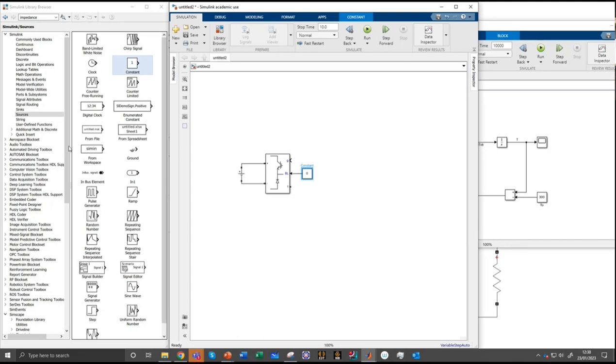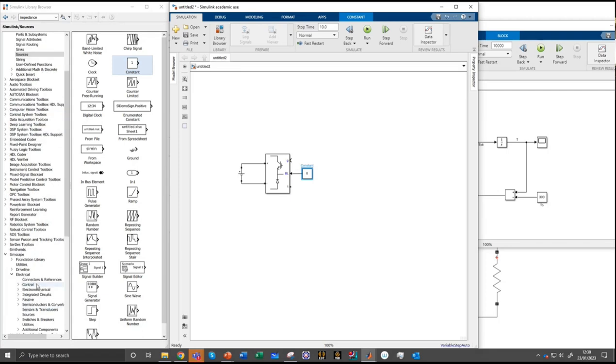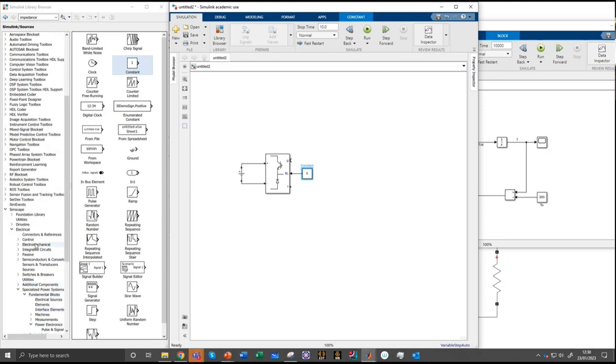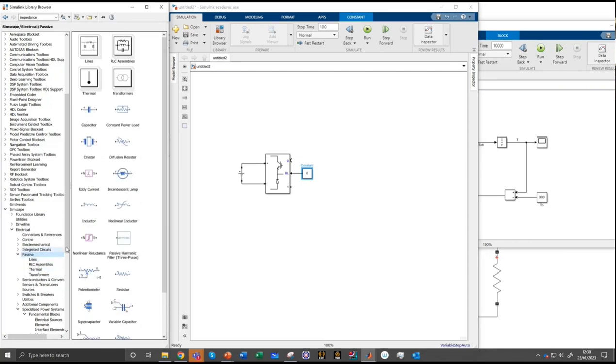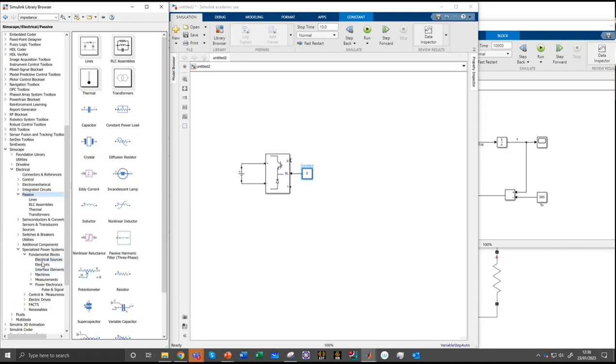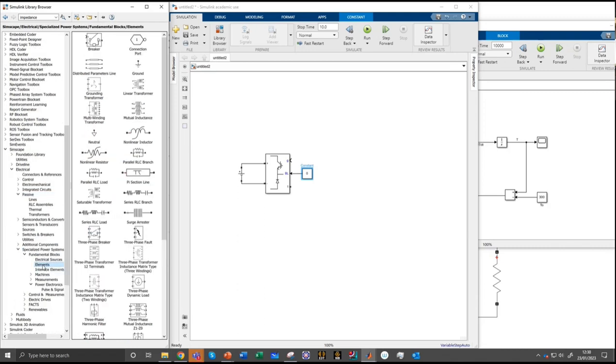And then we need to bring in an inductor, so back to Simulink. And there are basically passives here. So I'm just going to go to the passives library. Oh, sorry, no, we are on specialized elements in here, right? So there's an RLC branch.